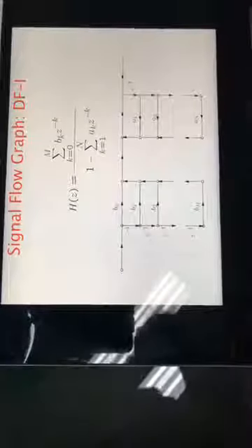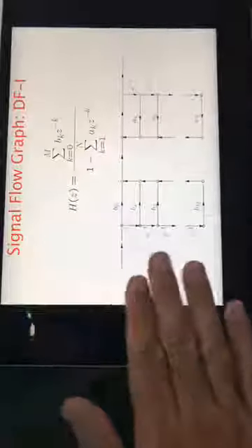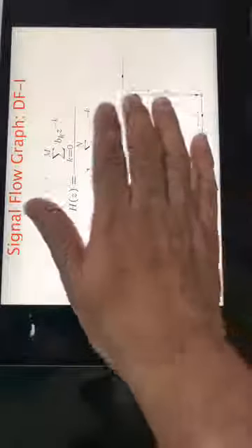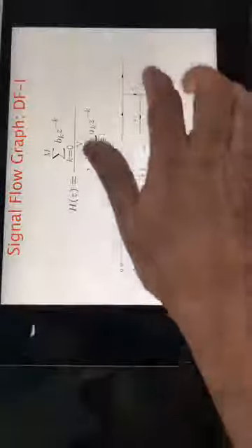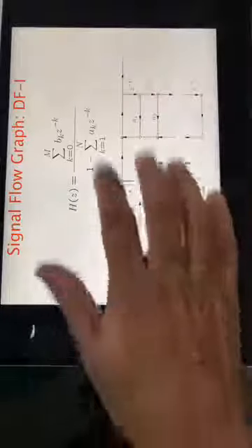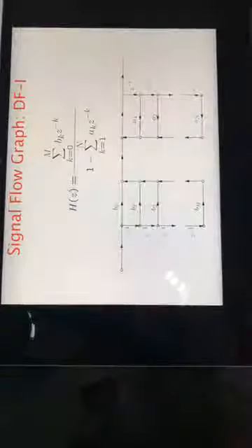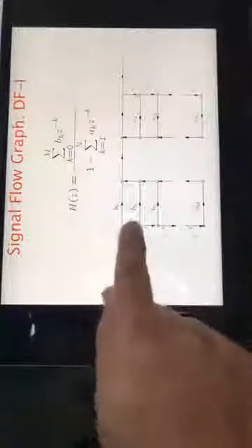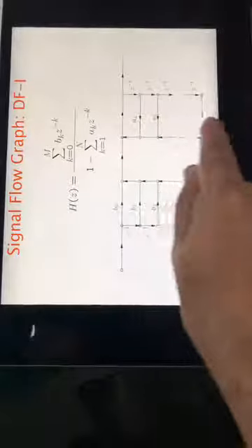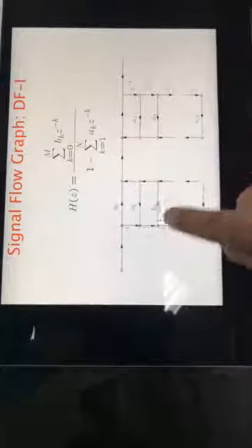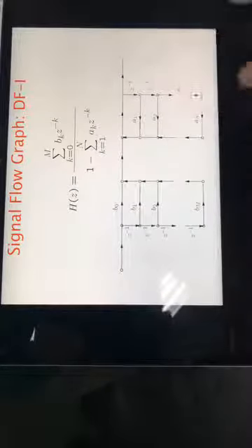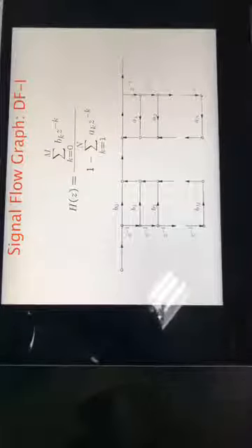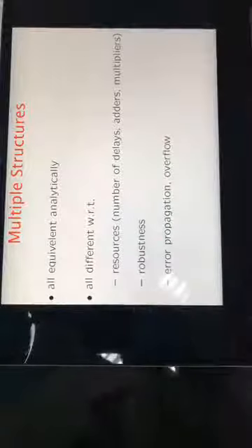So this is the same signal flow graph for direct form 1. There are registers, b's, y of n, previous values of y of n, multipliers, and as I mentioned in the exam, if you have drawn this and you are given a transfer function, all you need to figure out is your b0, b1, b2, and a1, a2, a3, and just put the constant values instead, and you are done with the answer. So you don't need to get into detail because you can just do the answers.